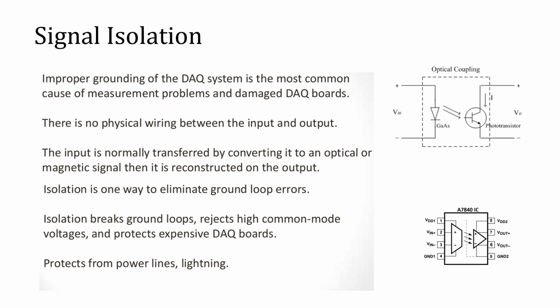Signal isolation. Now, what is isolation and why is this important? Isolation means when we have a circuit A and we want to give that information to circuit B. We want to isolate the information available on this side from this side. The reason being, it may be possible that circuit A is working at, let's say, 5 volt and the B circuit is working at 12 volt.